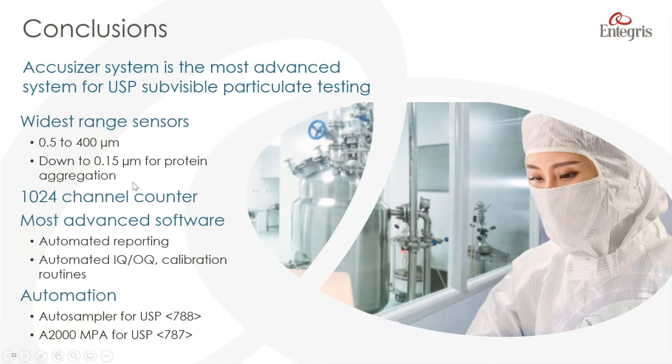We only need to measure at 2 size ranges, 10 and 25 microns, right? But we actually have a counter with 1,024 channels. And you don't need that for the reporting, but when you do things like the sensor resolution test or honing in your calibration curve to pass the USP count accuracy test, that's a terrific advantage.